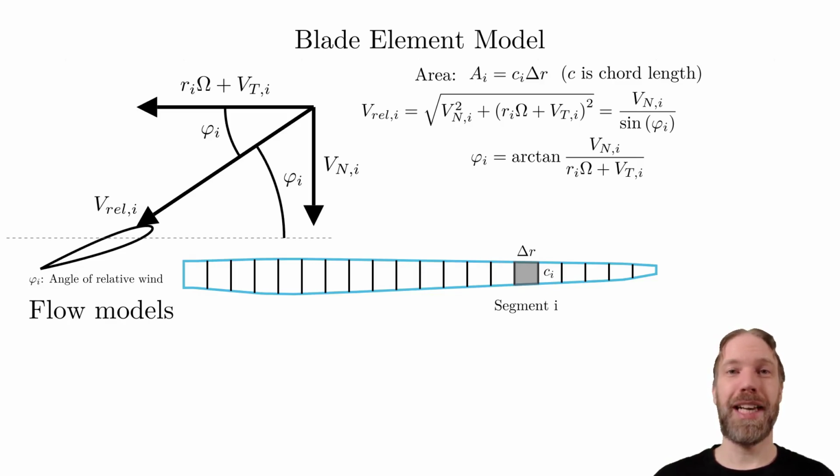The first approach here is the actuated disk model. Here one approximates the turbine as a flat disk with a pressure drop similar to our best theory. The flow can be either stationary or one can run the simulation time dependent.